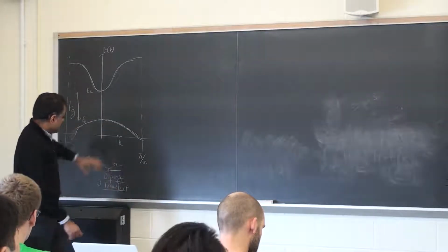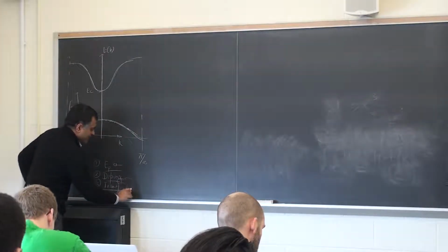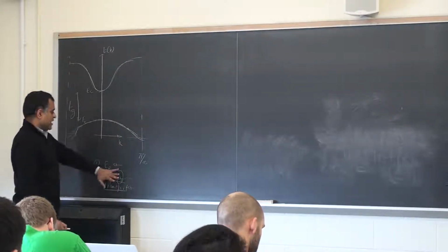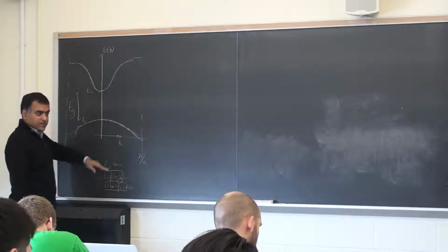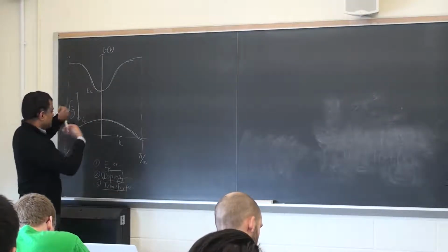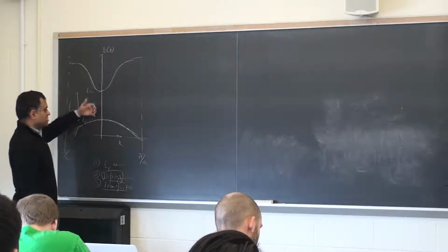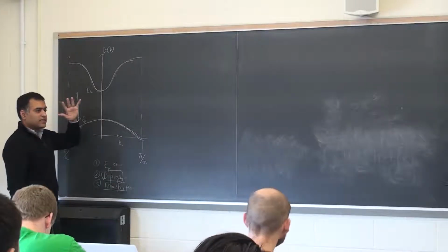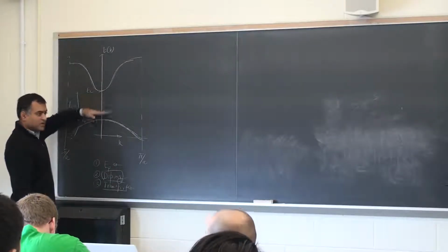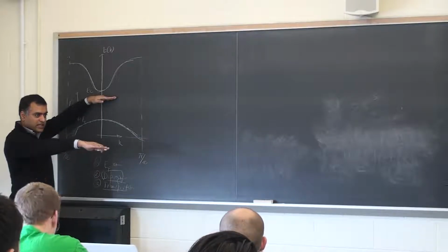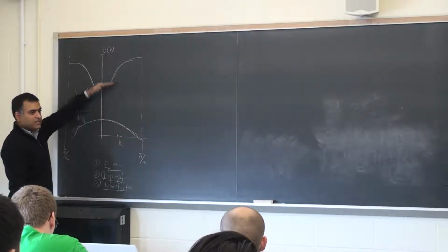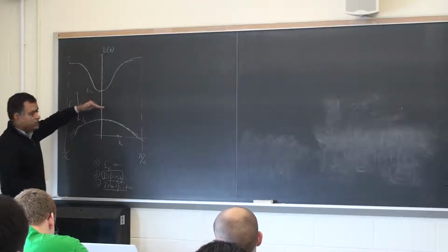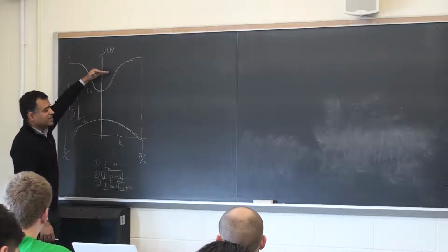Okay, so we'll look at these three things today. As we move along, we'll see that there are many other ways of putting carriers in a semiconductor other than doping. Doping is you chemically substitute certain atoms with extra electrons or missing electrons, but I can electrostatically change the Fermi level, and that would be gating with an electric gate. Capacitive gating, you can move the Fermi level up or down, and that's the principle for most field effect transistors,